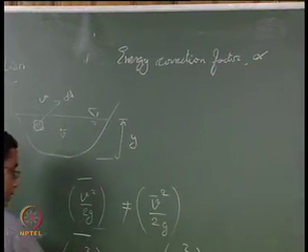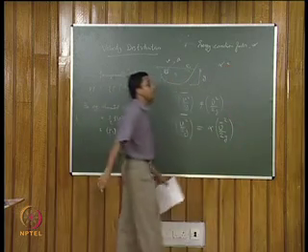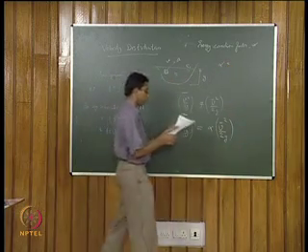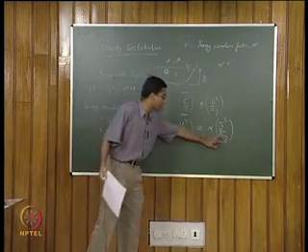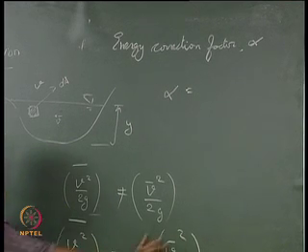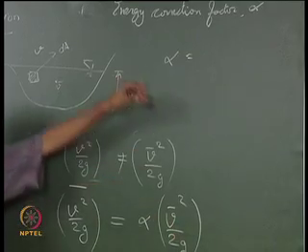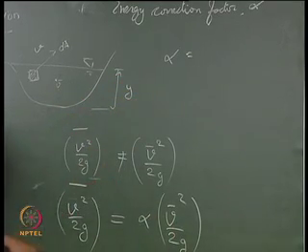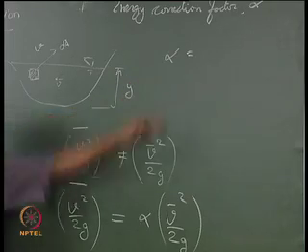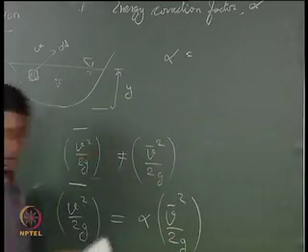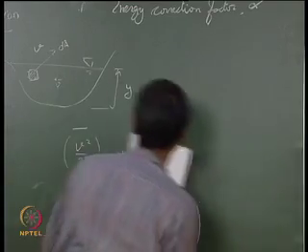alpha, and this alpha you can easily define in the following form. The kinetic energy obtained after incorporating the alpha term with the mean velocity and the kinetic energy obtained using your general velocity term should match, or I can write it in the following form, as the kinetic energy should match for both cases.